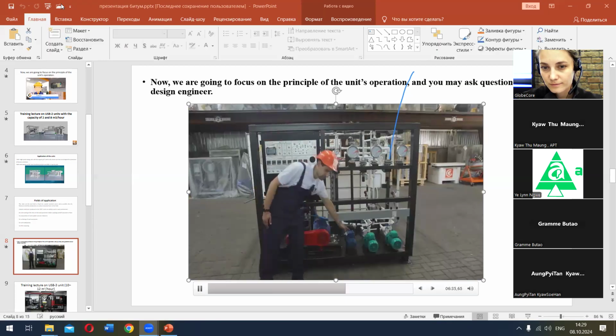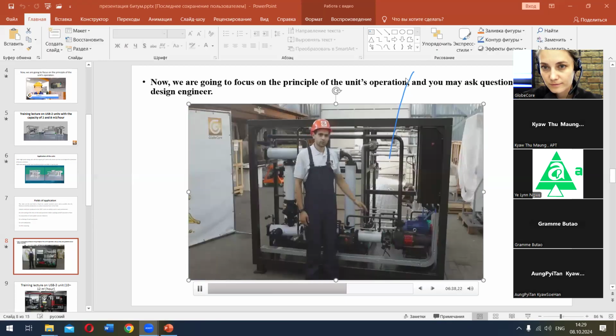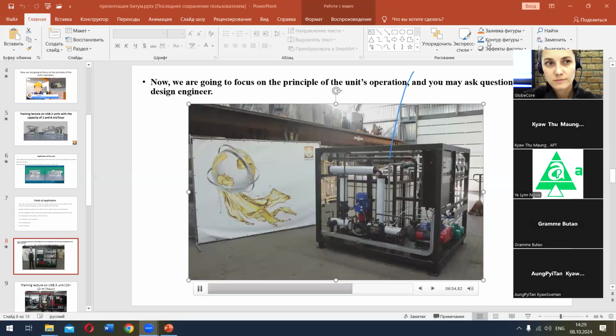Then, the water phase and bitumen are mixed in the mixer. In order to further stabilize and obtain the finished product, the liquid enters the mill, after which, at the mill outlet, it enters the finished product output pipeline. The finished product is fed into the finished product storage tank where it is stored at a temperature of 40 to 60 degrees Celsius. Owing to the design of the installed mill, the tooling of which has a special profile that allows homogenizing the bitumen with additives, we obtain a high-quality product in one pass.